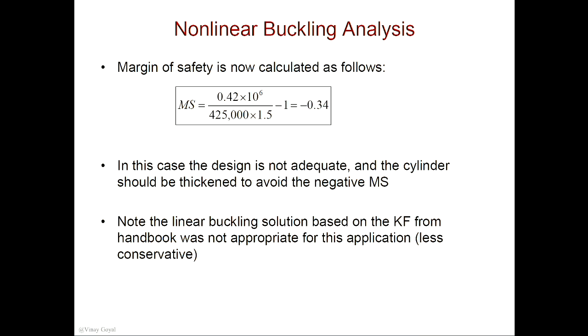You have a cylinder. So for a beam, if you do an experiment in the lab, I think it's going to match pretty well, not too bad, when the buckling occurs. But when you go to a shell, because the mode shapes are typically local waviness in the wall, as seen also by some of the experiments we saw, the pictures, then any small imperfection can actually make the shell buckle. And it turns out the buckling for a shell is unstable. So therefore, the linear buckling solution will not match the experiments.